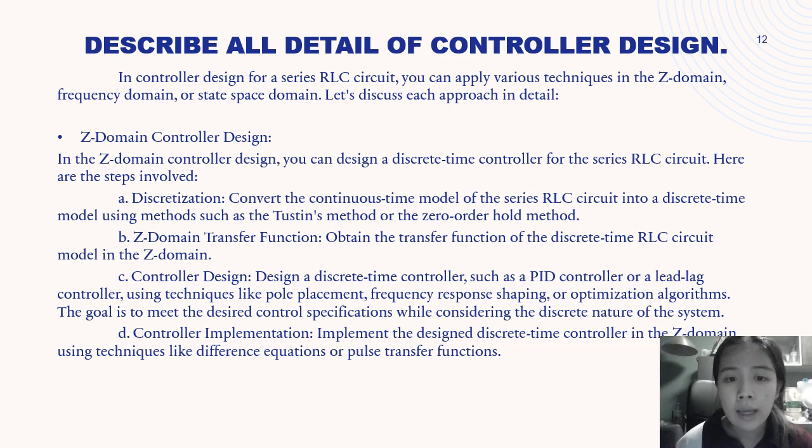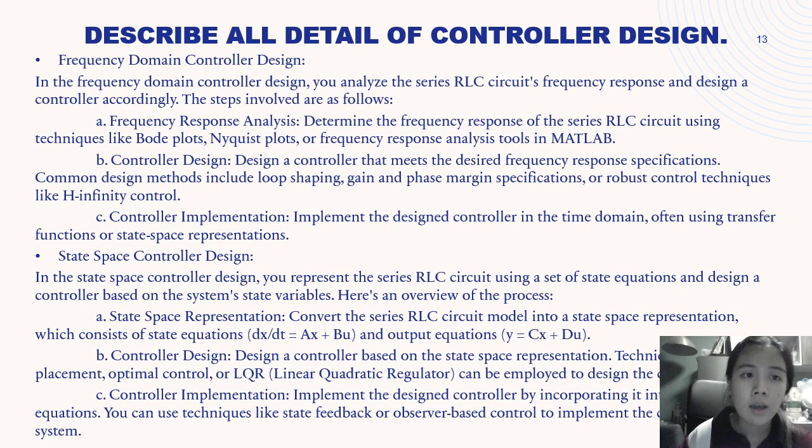And controller design is to design a discrete-time controller such as a PID controller or a lead-lag controller using techniques like pole placement, frequency response shaping, or optimization algorithms. And the controller implementation is to implement the discrete-time controller in the Z domain using techniques like difference equation or pulse transfer function.